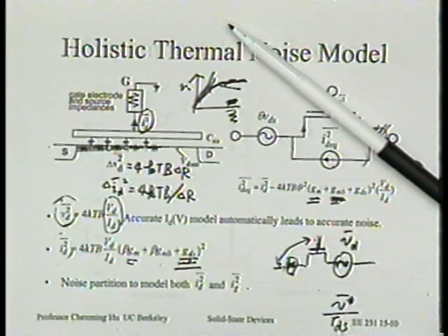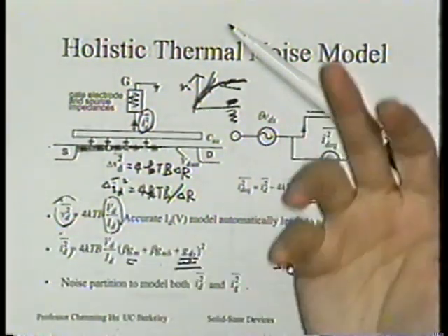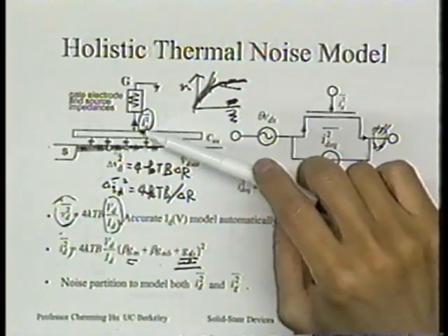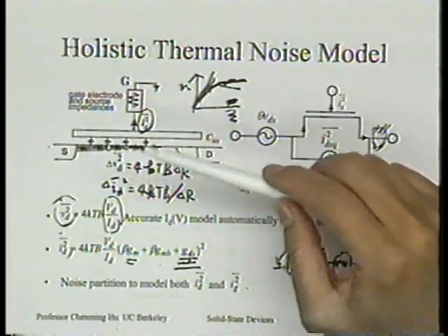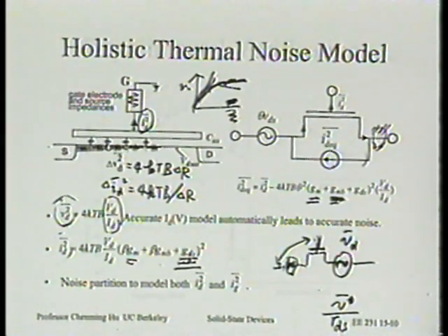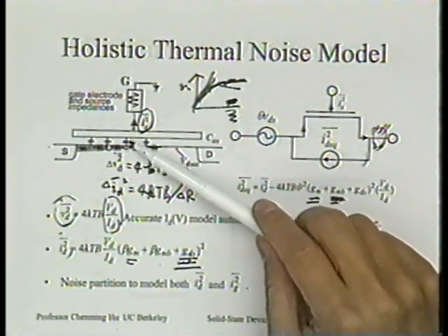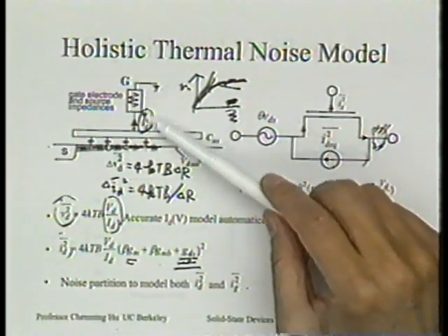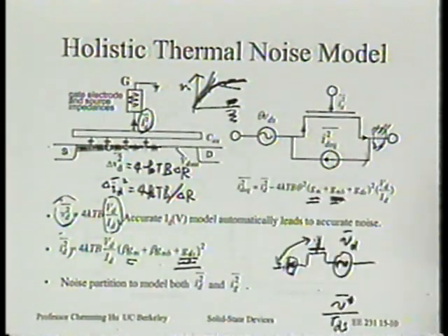Or just one of them? If so, which one? I'll make it easier. Let's concentrate on the gate electrode resistance, just the polygate resistance. Is that effective in translating this gate current into a gate voltage? Because the noise source forces the current to flow through the gate circuit, would the poly resistance then produce a voltage? Yes, right?